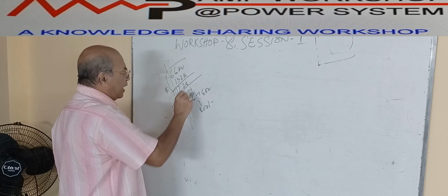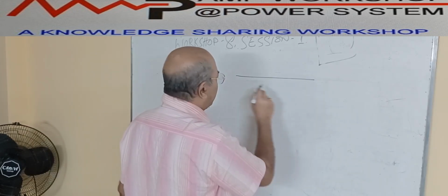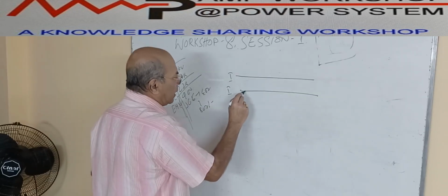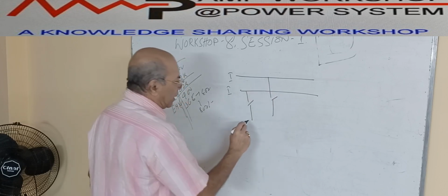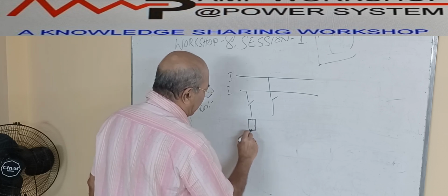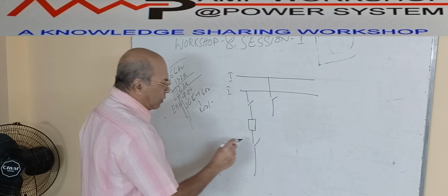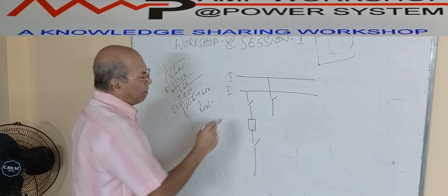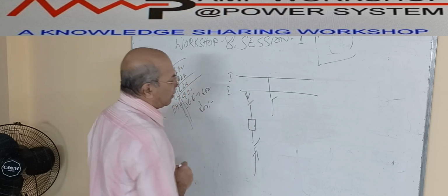When they go to the EHV operation, in that case this busbar arrangement again, suppose this is a dual busbar arrangement, this is bus 1, bus 2. Here also we have an isolator over here, here we have an isolator over here. Now we have a circuit breaker over here, but here on the load side also we put another isolator, because for the extra high voltage or high voltage system, power can feed from both ways. This way power can feed, this way power can feed.